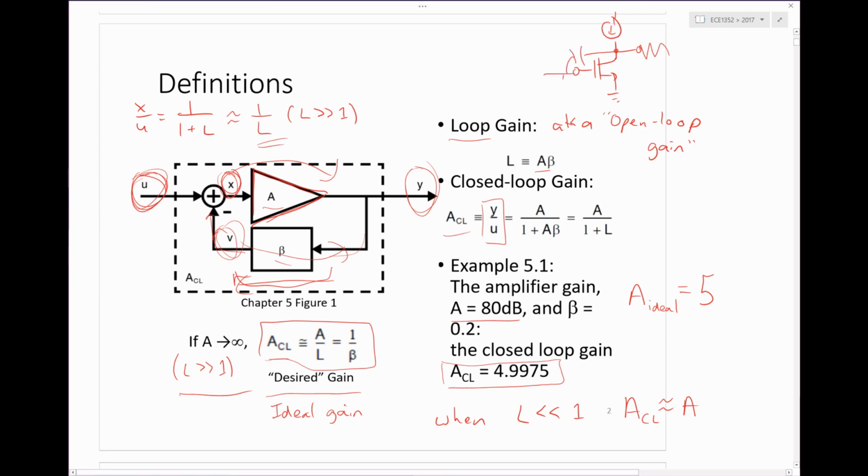there's all these capacitances here. So let's say there's CGD over here. Here's CGS. Maybe there's other capacitances connected there. So even putting aside everything else, right away you've got just a passive voltage divider there, so that some fraction of the test signal at the output will appear at the input. Okay. So right there you see an example of how there is some reverse transmission here. And that's not at all taken into account in this picture.